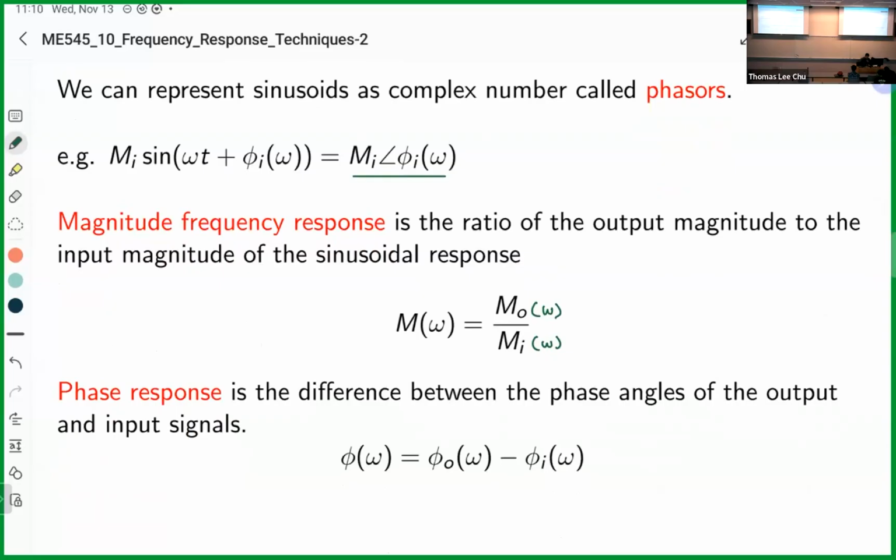With the phase response, we're always going to have a phase delay, meaning that when we put something into a system and then we watch it react, it's not going to react before the input. So there's always going to be a phase lag. We always have a phase lag. Locally, we might have a system where the phase is ahead, but overall, the system is always going to be in phase lag. All real systems.